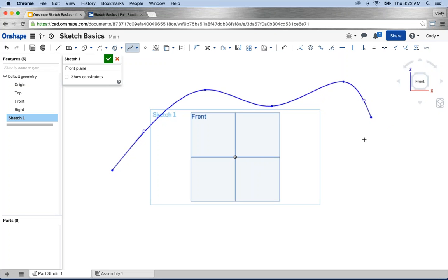So once you've finished your last point, or of course you can go back and select it in the toolbar, but it does not exit. You'll have to exit it. Some other things I like to point out, you can manipulate afterwards. So if I escape out of spline here, you'll see if I left click and drag, I can move these points. And this is what I mean by fine tuning or manipulating the end result. I can grab and drag these spline points around.